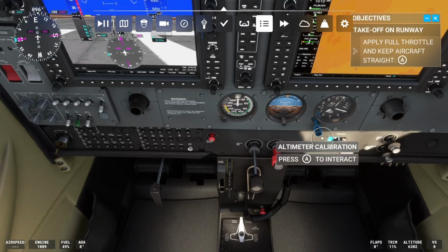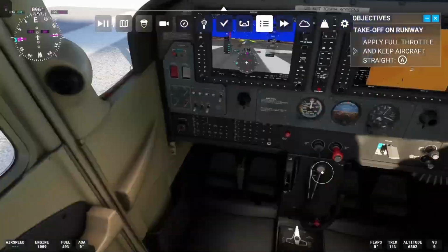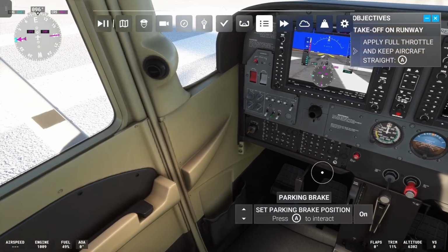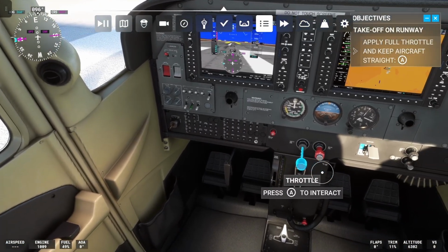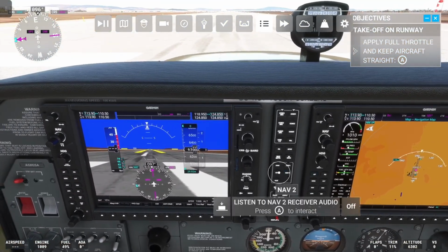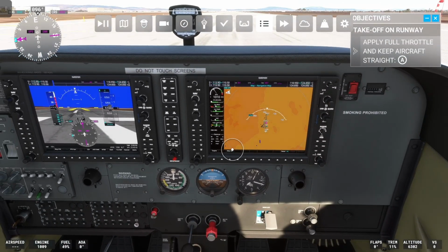Now we move on to a phase before takeoff run-up. Doors and windows are now to be closed, which they are. That is a check. Brakes are set. That is a check. Mixture rich, and now revolutions at 1,700. So, looks like our RPMs move to the right panel here. 1,700. So we put in some throttle. Let's see. Put in some throttle.